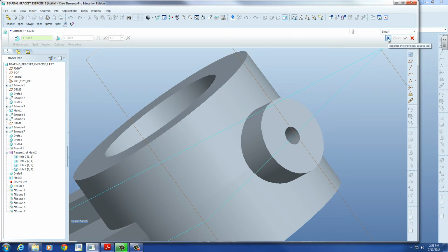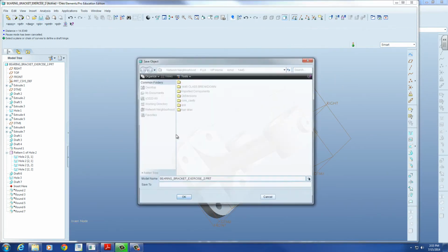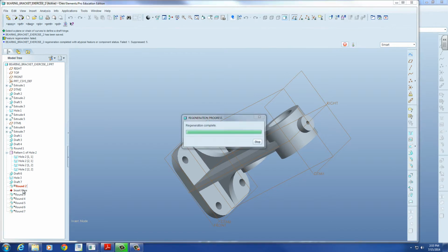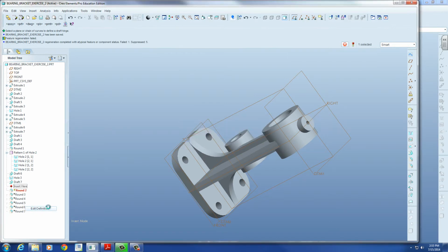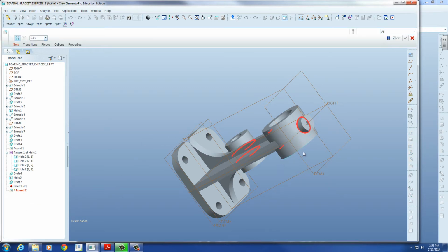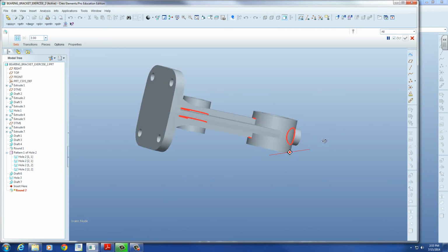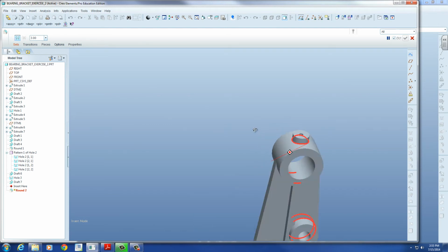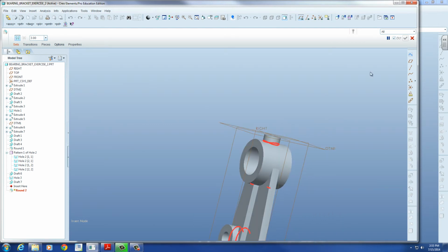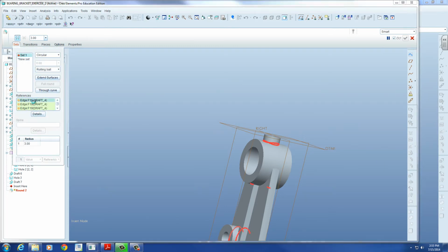And sometimes when you need an absolute, you might revolve something. Okay. That's going to be almost negligible. I'm going to save this again. Let's see what these rounds do. Oh! Failed on the first one. It's not got complete rounds now that we have split draft. It's not going all the way to the... What we're looking for is a failed edge. Found them. All of them.